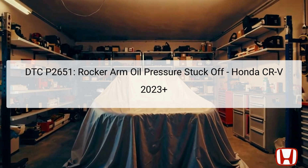The diagnostic trouble code, DTC P2651, signifies a problem with the rocker arm oil pressure in a Honda CR-V 2023 or newer model. The error indicates that the rocker arm oil pressure sensor output remains low when the rocker arm oil control solenoid is activated. Essentially, the engine's powertrain control module, PCM, recognizes this anomaly, suggesting possible issues within the VTEC, variable valve timing and